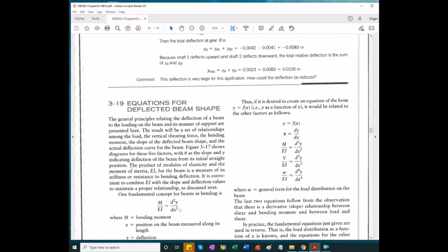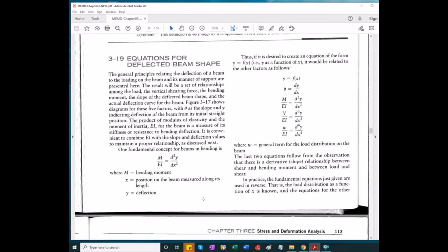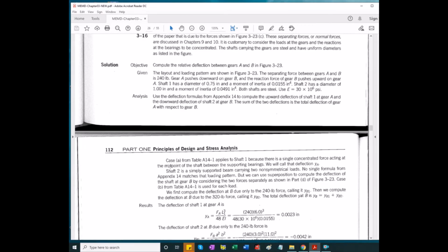We can use successive integration discussed in strength of materials. So the beam equation, moment over stiffness along the beam, and this could change by changing the diameter. Say if you have a stepped shaft, I changes with location. In the majority of cases, of course, we have the same material, but cross section can change, and area moment of inertia can change, equals the second derivative of the deflection of the shaft.